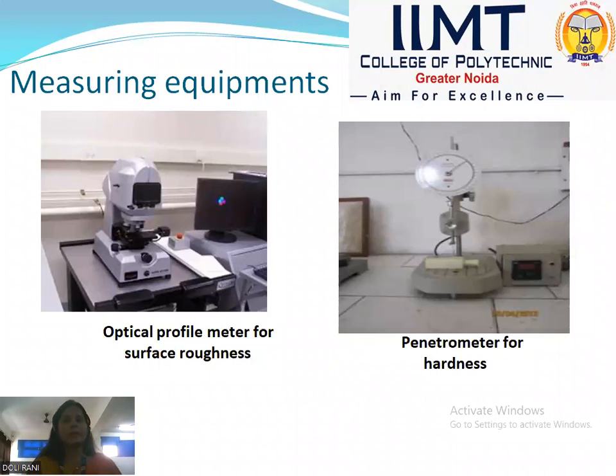As we are using a microwave oven for dewaxing, the same wax is used again and again, so the properties can be reduced, or some impurities can be added into the wax pattern. So we will check the properties. If it is giving good properties, then we can use the same wax again for a different pattern, or for making another product.